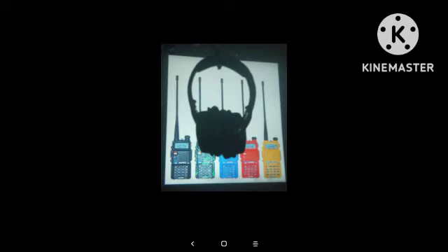27. A transformer has a 240 volt primary that draws a current of 250 milliamps from the mains supply. Assuming no losses, what current will be available from a 12 volt secondary? 5 amps. 28. The fact that energy transfer from primary to secondary windings in a power transformer is not perfect is indicated by warm iron laminations.